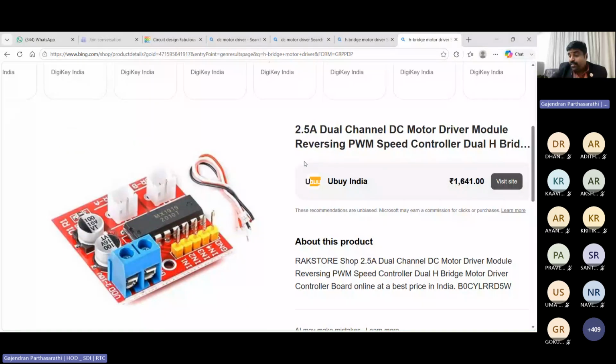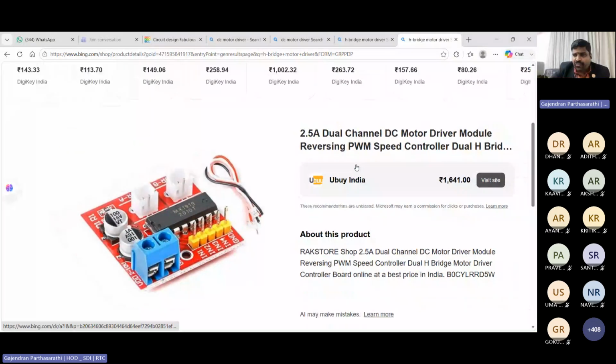In this, we learned a new concept last week that is printed here. Can you identify the new concept we learned in the last class? That is highlighted over here. It is one abbreviation. H bridge motor driver. Very good. PWM, pulse width modulation. Using the pulse width modulation technique, we can give an input to this motor driver. This driver will perform the speed control.